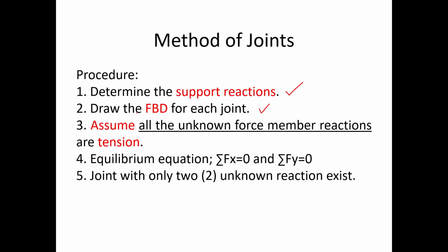So next, we need to assume that all our unknown force member reactions are tension. But I really don't recommend this one. It's possible, but most likely it will create confusion, because if you're going to assume tension forces and once you solve this particular member the value is negative, the rule is you're going to make it in compression. So go ahead and erase your answers.